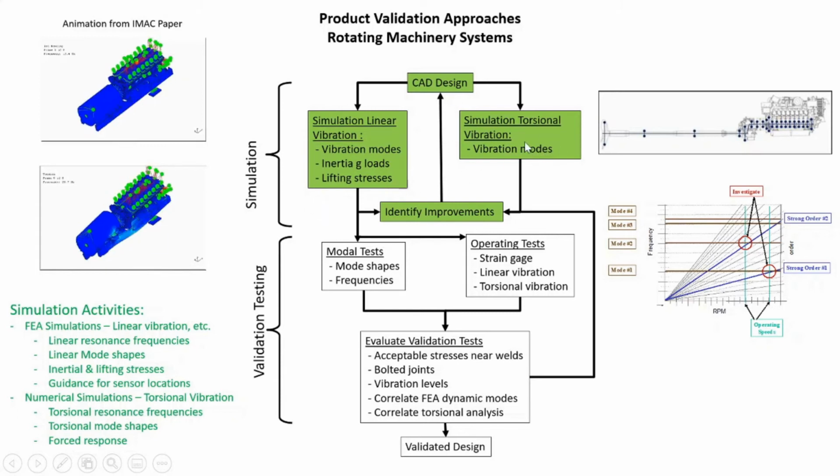Also, we look at the torsional vibration. And this again is aimed at looking at torsional vibration modes, pretty much with a numerical lumped mass type of analysis that will give us the torsional resonant frequencies, mode shapes, and even the forced response of the system.